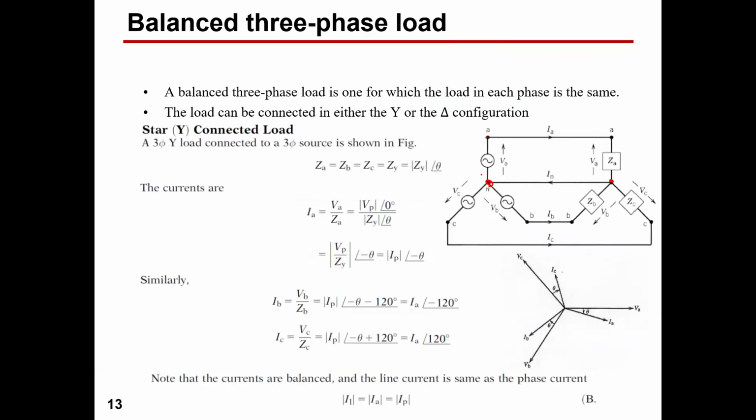So here, guys, this supply is Y, and this load is Y. I definitely can say VA is connected in series with ZA, correct? Even if we have a transmission line, I assume that this is the generation, this is the load, and I have a transmission line in between. So I can connect all of them in series together.